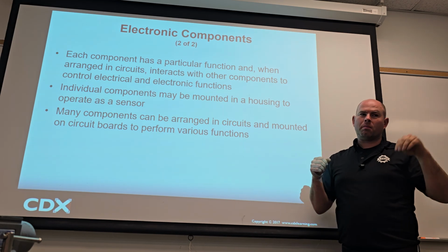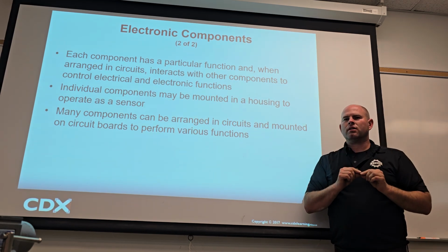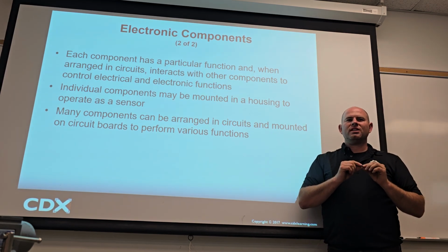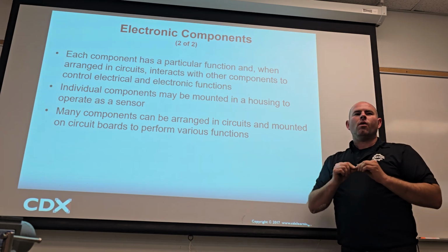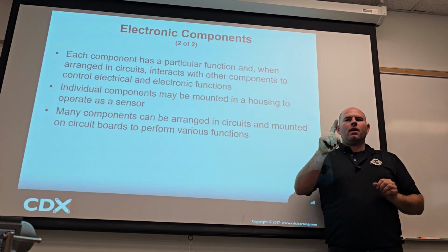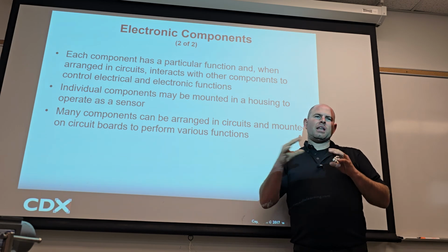Specifically, that's true. It's not giving power. What part do you think is wrong in there? The ground? In this one, it was not the ground. One transistor was bad, but we're going to replace the whole ECU, mainly because of one transistor.